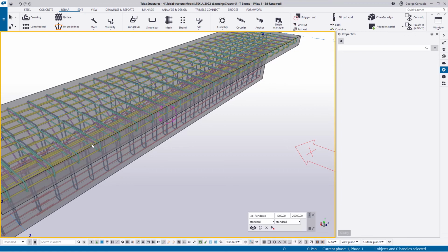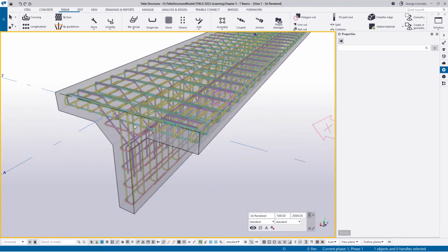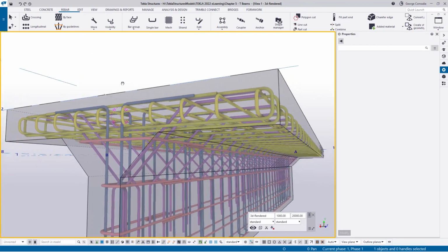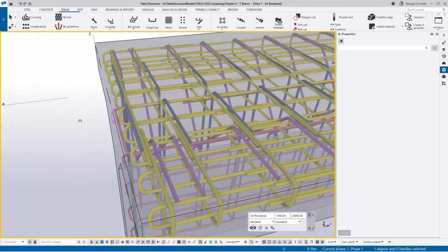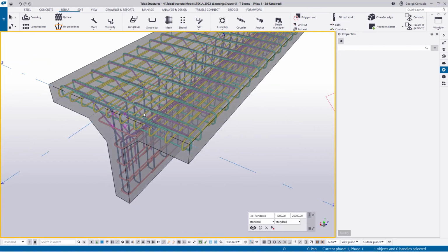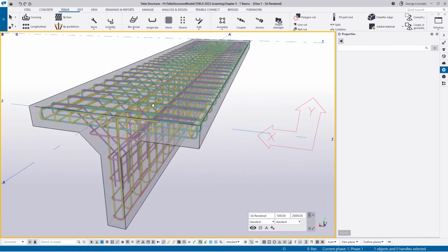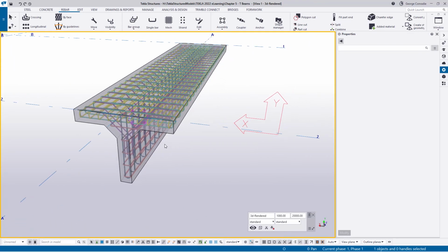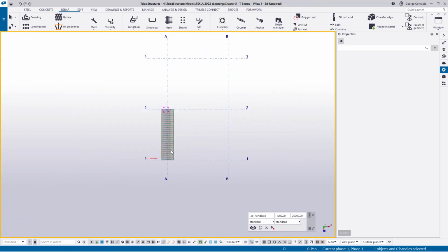It's easy to do in rebar sets. You don't have to remodel. You just click and swap. And we didn't calculate any bar lengths or anything like that. So I think this is a pretty good solution and a very good application for rebar sets. Sometimes components are really, really fast. But in this case, I think rebar sets is equally fast.